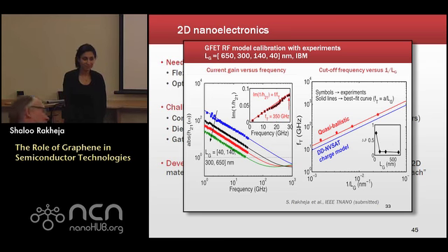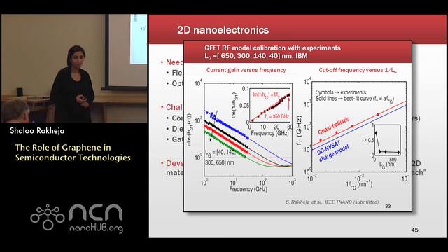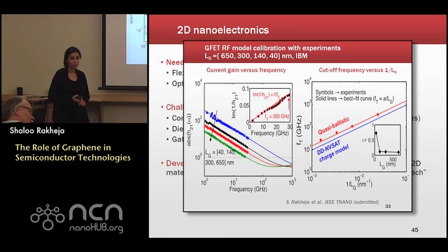So coming back to the channel length scaling, the output characteristics actually show smaller and smaller on-off ratio. And from your physical model extraction, can you tell me the physics behind it, why the on-off ratio actually gets smaller when the channel length shrinks? I think this is a very good question, and I think that in these devices it gets limited, and it's a very involved philosophical question right now for me. And I think that contacts tend to play a bigger and bigger role as channel length gets shorter and shorter.